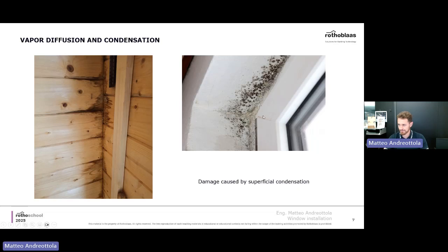Airtight problem means that the corner detail was not done in the right way, meaning you have some cold air coming inside of the building, exactly where the corner of the window is. This is a super, super common mistake. Just to understand how common it is as a mistake, I will bring to you this example.